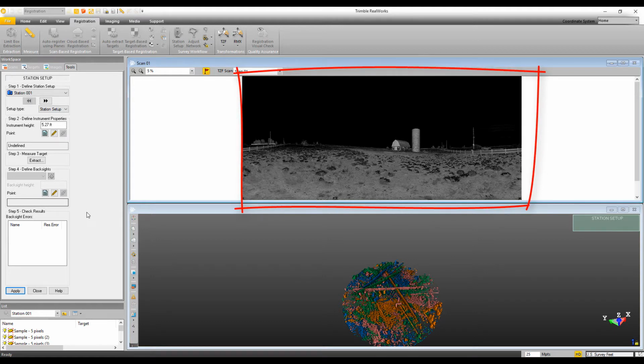And once that scan's complete, I can isolate a specific area and scan it at a different resolution. So overall, this was just a quick 3-minute scan that I did out there, medium density. But there were some targets that were a little bit farther away, maybe 150 feet. So I did a higher density area scan on those targets. Again, I mentioned earlier, I was using the 100 millimeter targets. These are fairly small spheres, and I wanted to make sure that I had enough points on those that I could process this once I got back to the office.